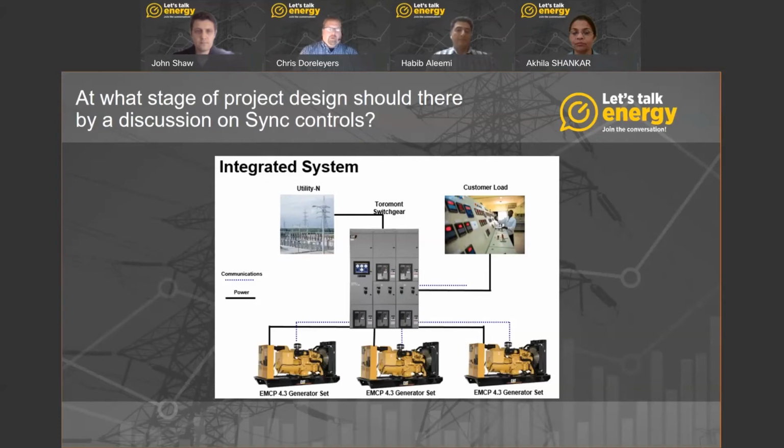Excellent. Thank you, Habib. And maybe just to add to that comment, if you're looking at a switchgear design and you're concerned about meeting 100 milliseconds for closed transition and your routing of permissives, understanding the cycle time of your breakers and working with your counterpart from your generator manufacturer, we can take a look at whether or not we have to use things like solid state relays.